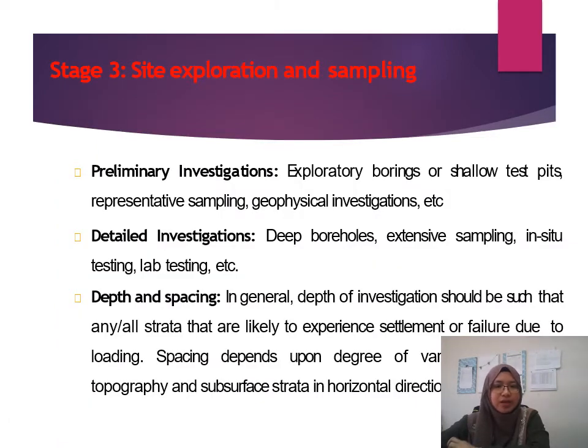Okay, so next is site exploration and sampling. It involves preliminary investigation, detailed investigation, depth, and spacing. For preliminary investigation: exploratory boring or shallow test pit, representative sample, geophysical investigation. So you start to explore your site. There are various types of exploration technique, for example, boring, trial pit, and so on.